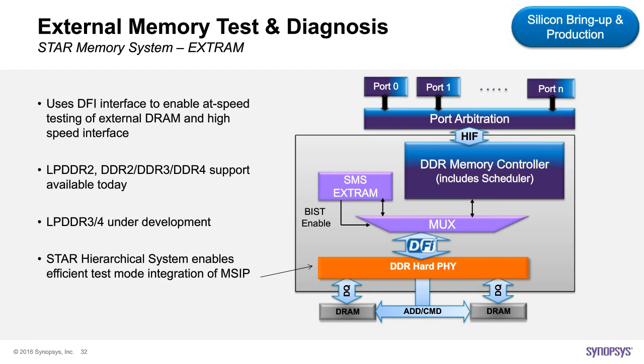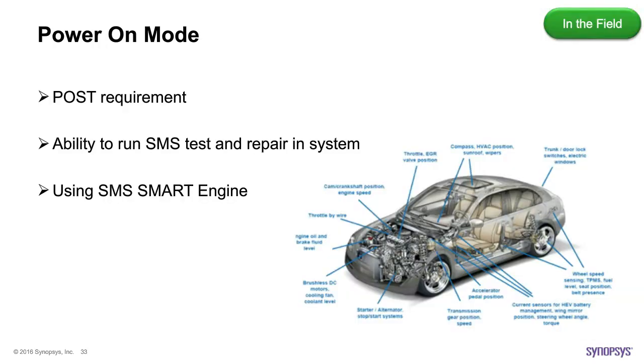Okay? So you see the orange PHY sitting in the SoC, and you see the controller in blue sitting behind it, and the SMS sitting in parallel to the controller and communicating via the PHY to the interconnect and the memory to provide us what is necessary. So again, this will help us to debug and help us reduce the risk upon manufacturing.